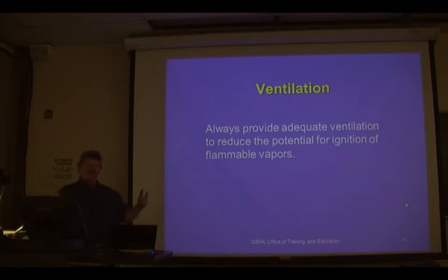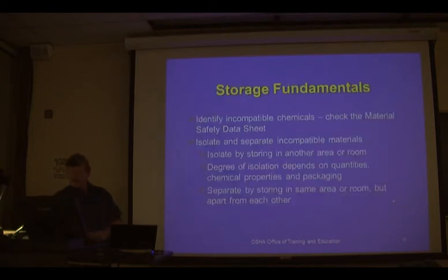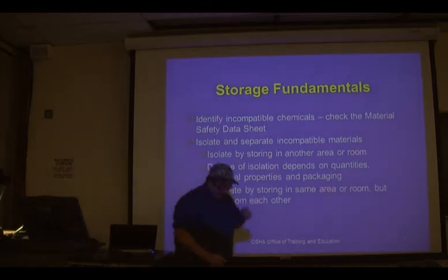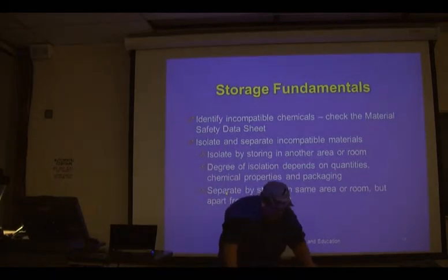You probably will have to write those again. Adequate ventilation, and it has to maintain below 1/4 of the lower flammable limit. It has to be enough ventilation to prevent buildup to 1/4 of the lower flammable limit. That's a better way to say it. I don't know if I wrote that in there or not. Look on your handout and see if I included those.